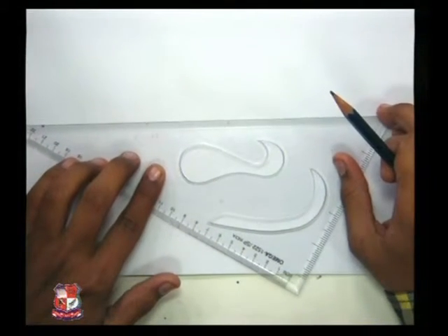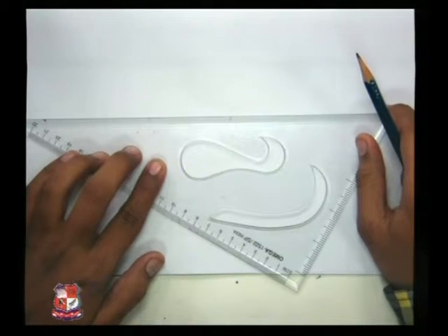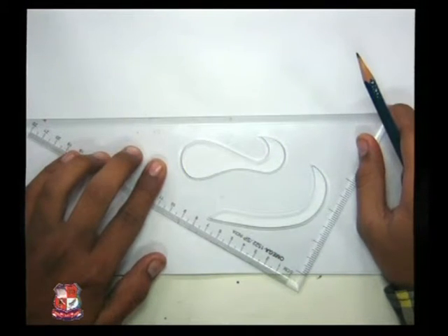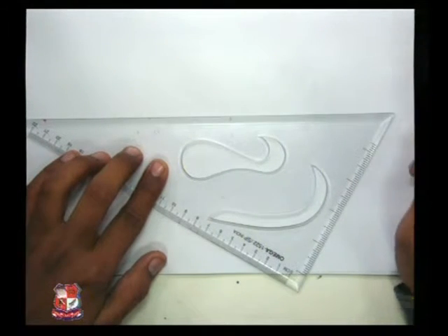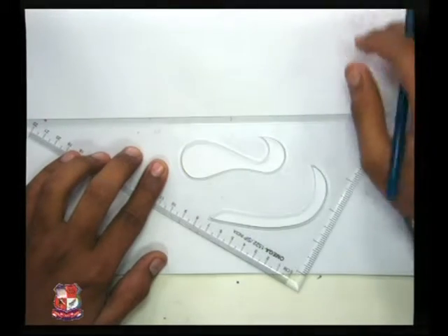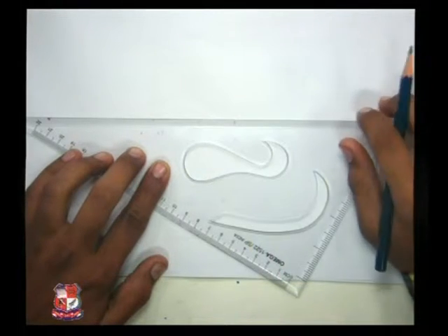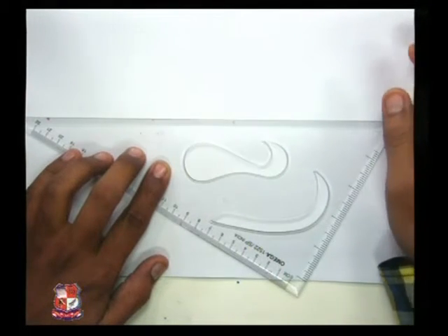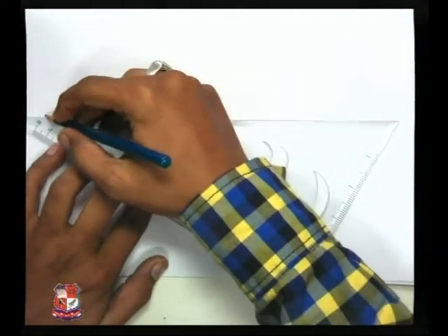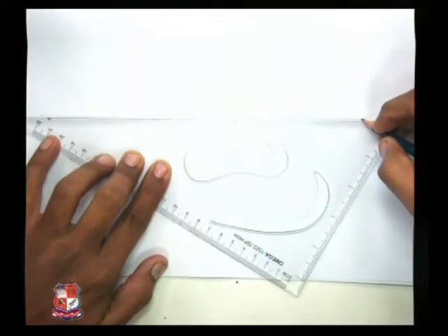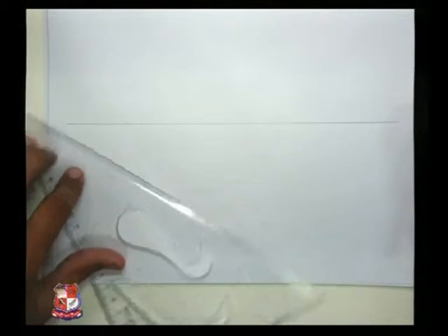First of all, we will draw a reference line. As it is using the first angle method, the top view will come in the bottom portion, so we will draw the elevation on the upper side of this paper. And the left hand side view will come on the right hand side, so we should draw the elevation on the left hand side of this paper. The upper left corner would be ideal to draw this problem.